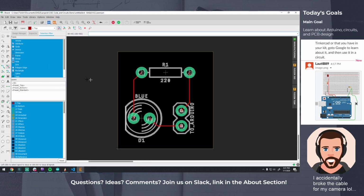Maybe we didn't like that, so we can come over here to the rip up. We can click one and delete it, or you can shift click, sorry, not shift click, is it control click? If you control click, you can completely rip them up. And we'll show you, so maybe we want to position it some other way. If you want to go, I don't know, out to here and then down in. And if we didn't like that, we could click on the move tool, sorry, not the route airwave tool, the move tool. And we can move things about and we can position them where we want.